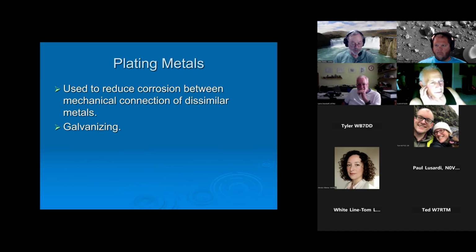So one of the things you can do is, if you have stainless steel, it's pretty easy and works really nicely to overlay that with a piece of copper or bronze, just a thin layer, and then overlay that with another layer of chromium or chrome. So that's the way you make a bumper. Trying to get chrome to stick to a steel bumper doesn't work. The two react to each other, and that's where you find bumpers with chrome falling off because something got in between and allowed a galvanic reaction and allowed those two to fall apart.